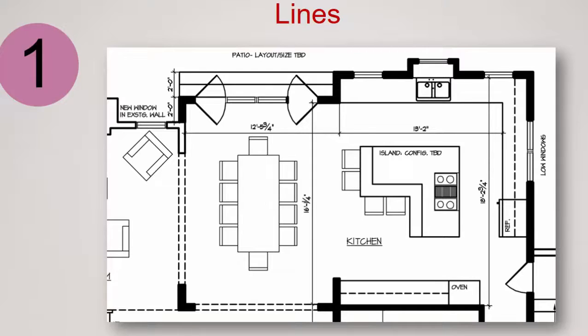In the case of the kitchen, over on the far right-hand side, you can see that there are lower cabinets with a sink and a refrigerator, but the dashed line above those cabinets represents the upper cabinets. Now you can't see them, they're somewhat hidden in this view because the plan view represents a slice of the wall section. So even though we cannot see the cabinets at the slice where this was taken, we know they exist. So we have to draw them as a hidden line or a dashed line.